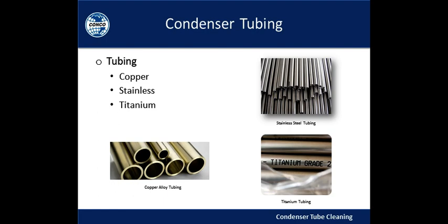On stainless tubes, the most important thing is to keep it clean. It's an excellent performing material. However, it does collect slime and particulate deposits. And one of the funny things about this material is it's used predominantly in the Midwestern United States. And in the Midwestern United States, there is an abundance of calcium in the cooling water and other, let's call them hard water conditions, that cause scale to plate out onto these tubes. Easily enough, it's removed, but nonetheless, there is a loss of performance up until that time.